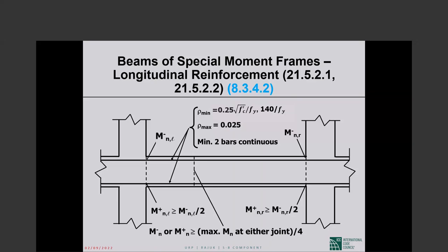net positive moment at the support section requiring bottom reinforcement. Okay, this is fundamental, this is important, but after every earthquake we see bottom cracks at supports because gravity thinking engineers simply would not provide that bottom reinforcement, which is easy to do. So this is a very, very important requirement. And then nowhere along the span of the beam can we have either positive moment strength or negative moment strength that is smaller than 1/4 of the larger amount of negative reinforcement provided at the two support sections. I said quite a bit. I think it is difficult to follow.